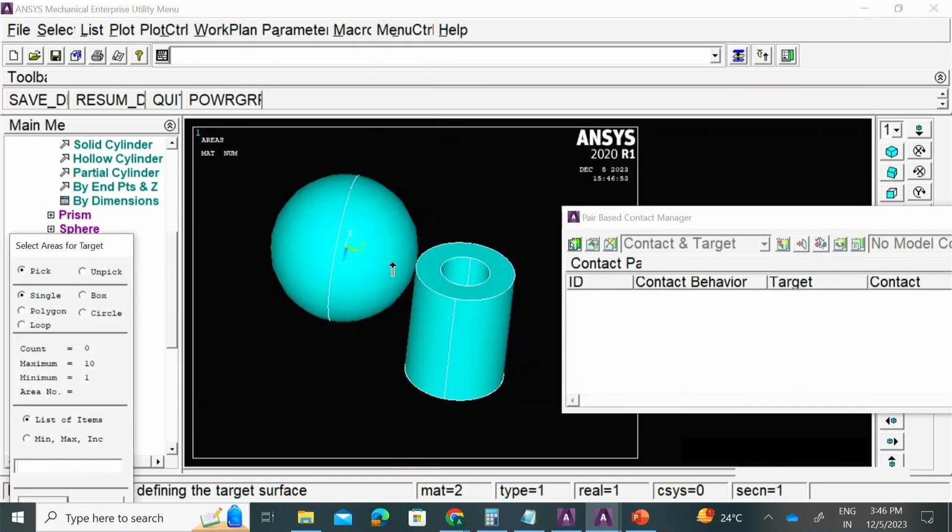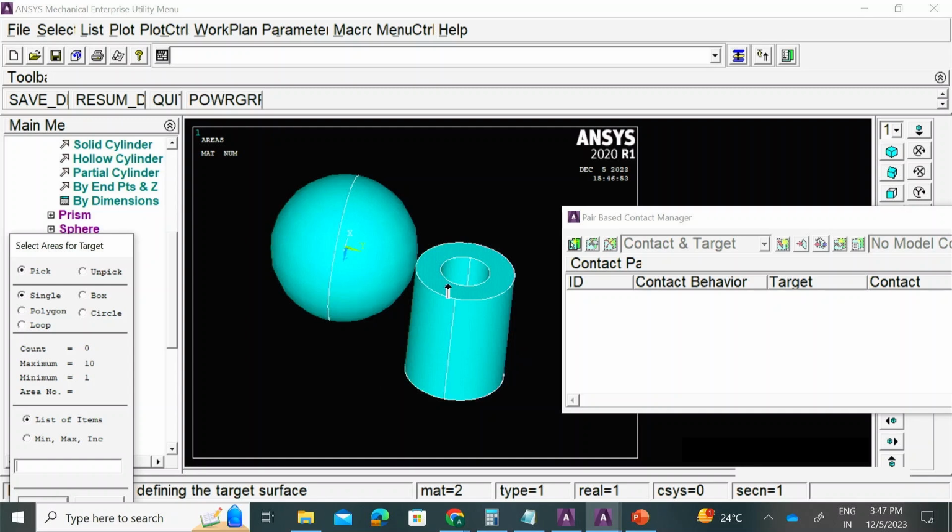Let's assume that there is a urinary incontinence, which is difficulty in urinating due to some prolapse or overlap or some level of forcing of the rectum on the bladder. Let's say that's the clinical condition which we are trying to address, right, or simulate. So my target would be the bladder and the contact would be the surface on the rectum. So let's select these outer surface.